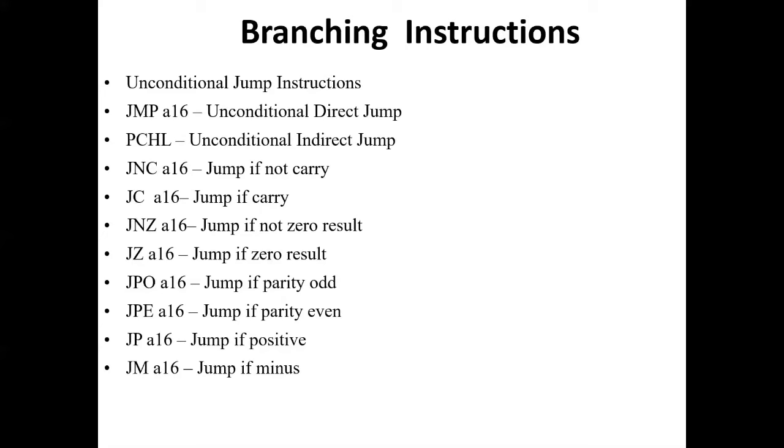Next is JNZ A16, jump if not zero result. JNZ is a mnemonic which stands for jump if not zero result. This instruction is used to jump to the address A16 provided in the instruction only if result is not 0, indicated by a zero flag value of 0. If zero flag value is 1, program flow continues sequentially.